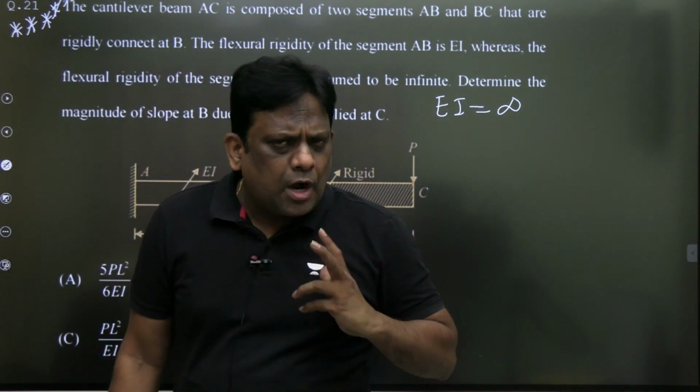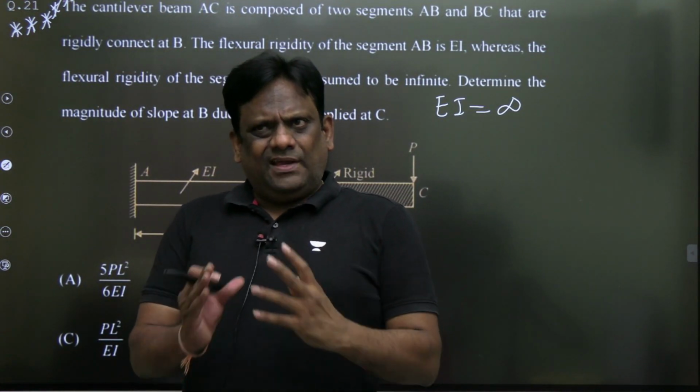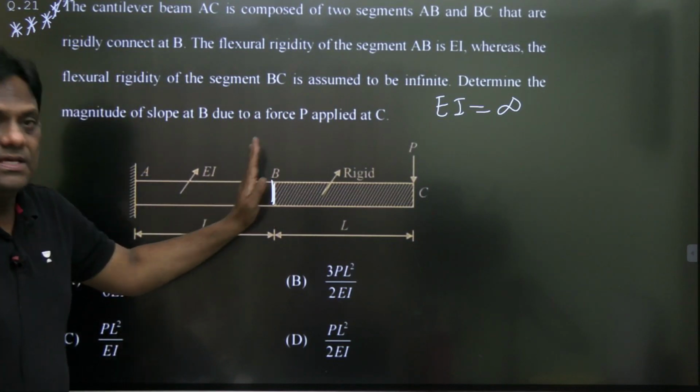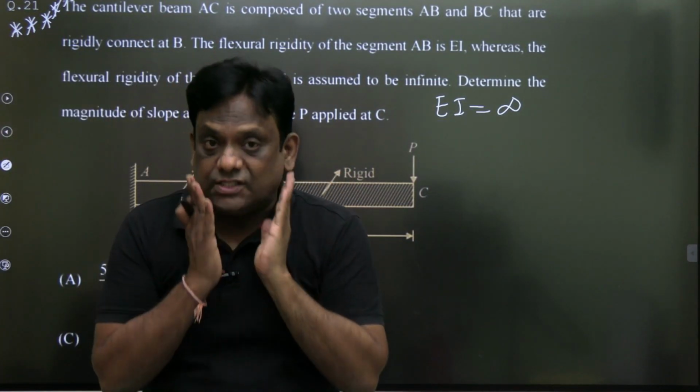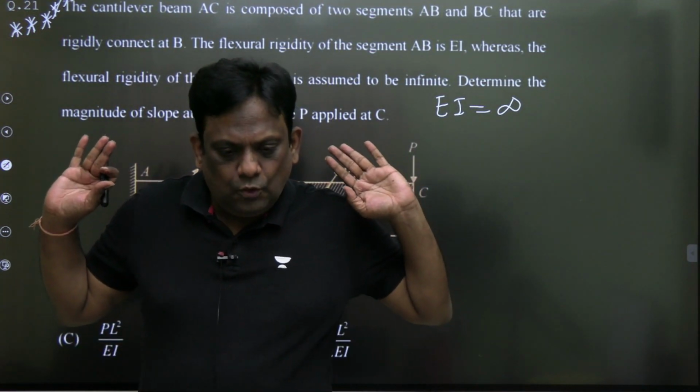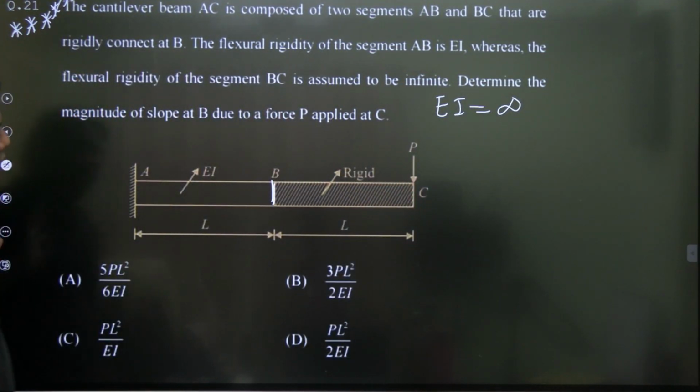Whenever you come across such questions, where there is a rigid member and a deformable member, this is a deformable member, and this is a rigid member, I request you to go for the strain energy method. No problem at all. So let's see how we proceed.